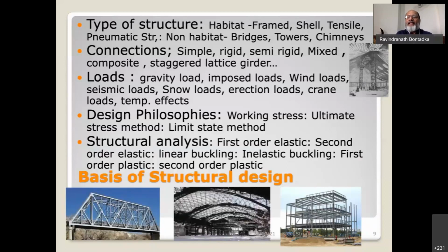Then the structural analysis depends on whether you're going for a first order elastic analysis or second order elastic analysis, where you consider only the elastic behavior of the structure, and then linear buckling is taken, then inelastic buckling is considered, then first order plastic or second order plastic analysis is considered. So all these things form the basis of our structural design. Though, of course, most of them have been covered in our academics, still one needs to get into what kind of basis you are looking at in all these things.